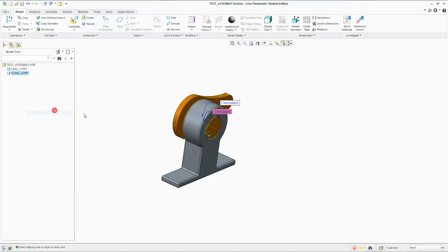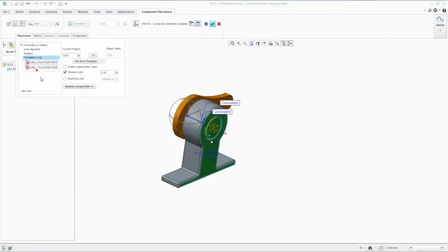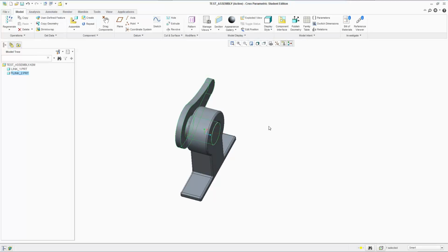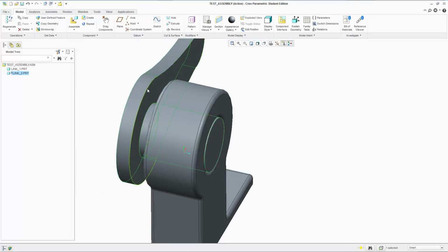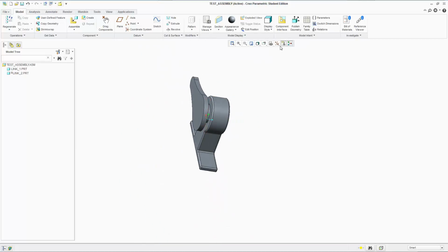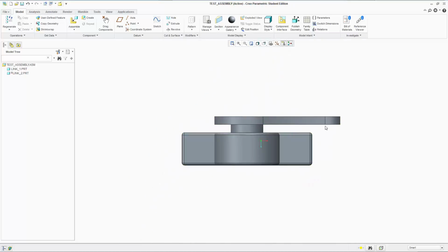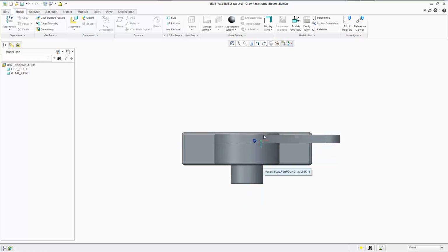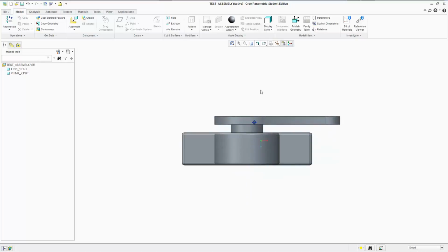Then I'm going to go to edit definition again, and translation axes. Now we're going to set a maximum limit. We want it to be realistic, so the maximum should be the distance of this tiny gap that you see here, from the top view. I want it to be able to slide just to here and then stop. Right now it's going further, but I want it to stop automatically like it does at the minimum limit.